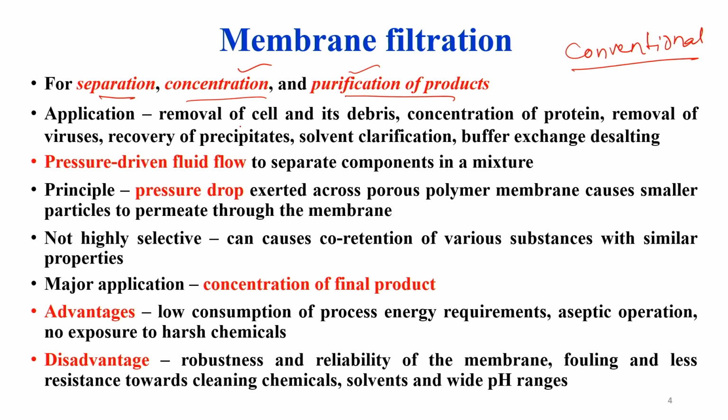Application, as I told, it is used for the removal of cells and debris, concentration of proteins, removal of viruses, recovery of precipitates, solvent clarification and buffer exchange. So, how does it work? Basically it is a pressure-driven fluid flow. So, delta P is the driving force to separate the components.